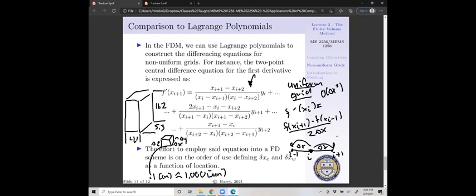Okay. Now, oftentimes, when you're doing certain types of modeling, certain types of physics, you're definitely going to go through a grid-independent study. So you're going to refine and refine and refine your mesh, and you're going to track the evolution of your solution, and hopefully it converges to a value. Now, for instance, in our modeling of these devices, we try and hit 40 microns for our max size.